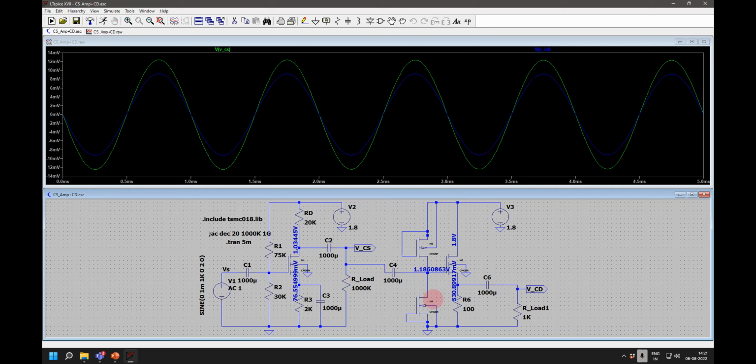No, actually you can think of it as a sub-threshold conduction region. There will be some currents in picoampere. So with respect to the PMOS, this is also off, this is also off. Both are in megaohms. But if you change the relative widths of these two transistors, you can adjust this operating voltage. Like I have kept it as 1.18 volt. If I want to change that, I can change the width of these transistors.